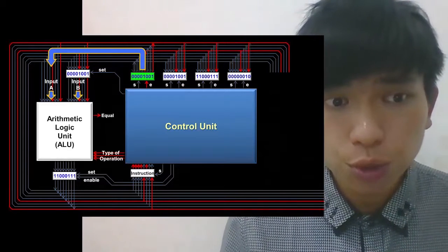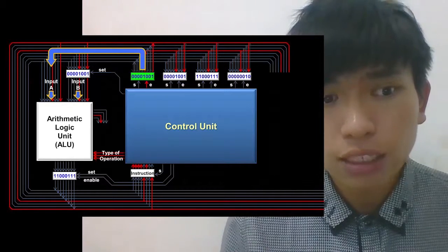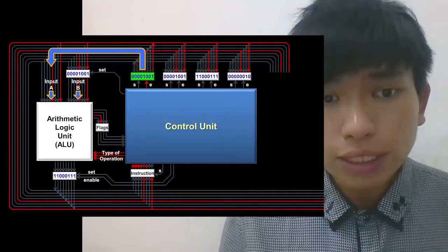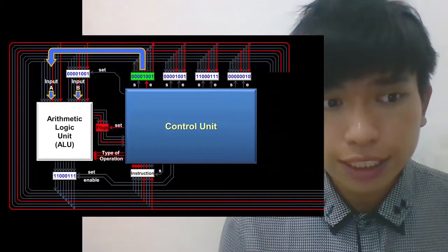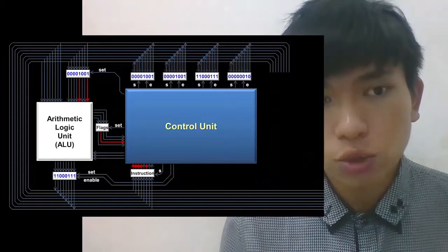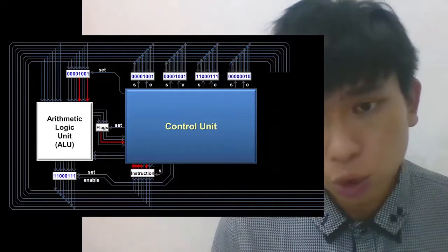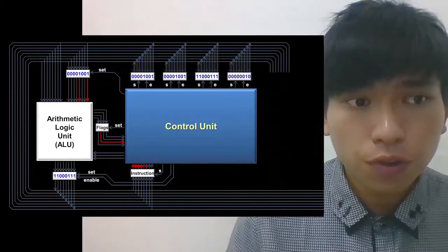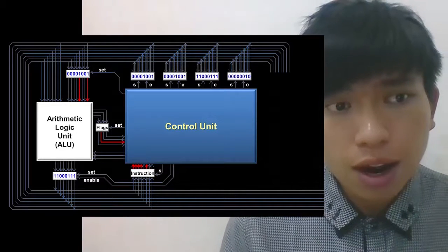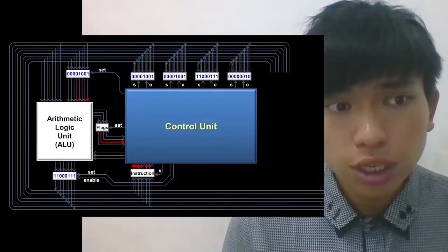Once the compare instruction is over, we still need the flags for the next instruction. So we use a flags register that has only 4 inputs and outputs, one for each flag. Once the set wire is turned on in the flags register, the CPU is finished with the compare instruction and will proceed to perform the next instruction from RAM. Generally, after the compare instruction comes a jump if instruction. This combination of compare and jump if is very common in computer programming. Anytime there is more than one possible path in a program, the computer uses these instructions to decide which way to go.